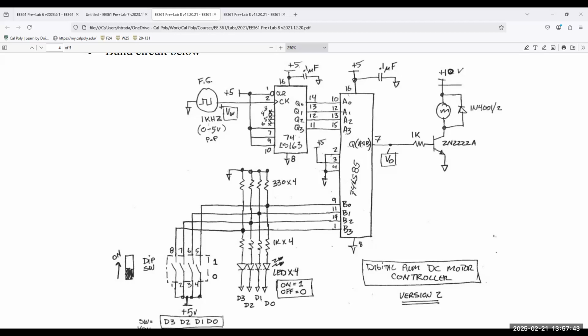Analog signal. Every time the comparator input went above 2.5 volts, the output of the comparator went to plus 5 volts. Anytime the sine wave went below 2.5 volts, it turned off. So you had a pulse that appeared. Output of the comparator was like a rectangular pulse. If you turn the dial of the potentiometer, the on time of that pulse would increase. If you lowered the voltage, the off time would increase. Okay. On time and off time.